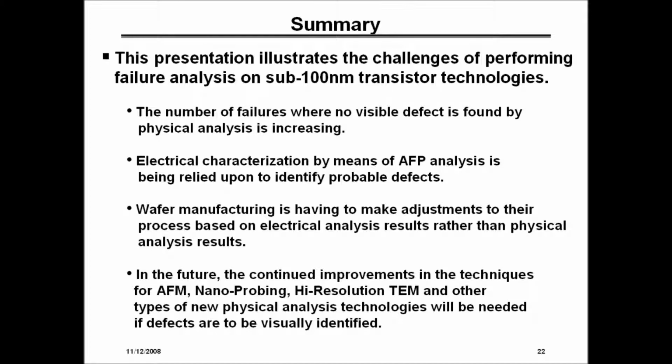However, for holography to work, it has to be heavily doped. So typically you see the source drain implant diffusions, but the lightly doped drains, as well as the lightly doped well, if you have bulk, don't show up very well, and so you're kind of limited by that. But as far as the source drain implants, they're very visible, and